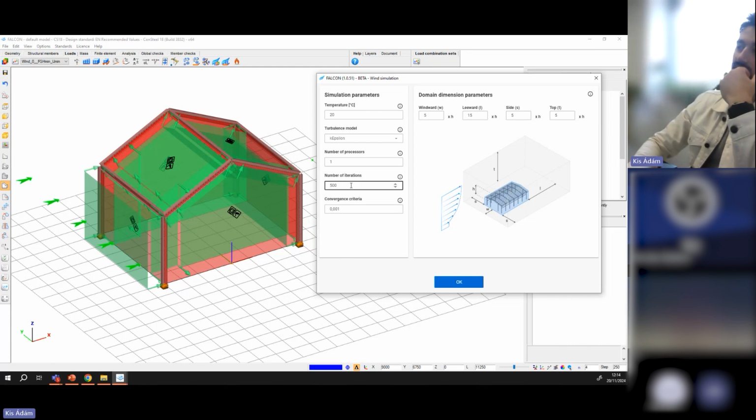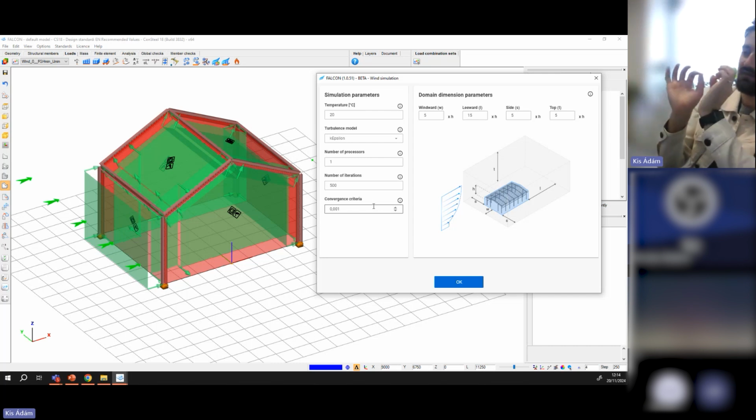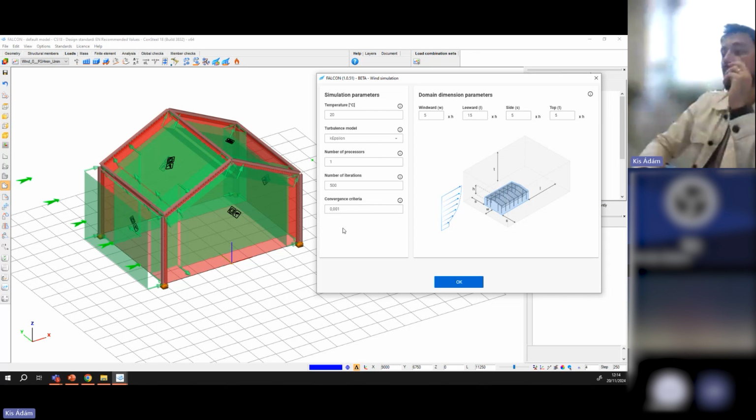Okay, you can define the number of iterations. If you don't have convergence, which in this scenario is a value meaning the difference between 2 iterations for all the fields, so in those 2 iterations you have specific pressure or velocity values, and if the difference is smaller than this convergence criterion, the result is considered converged.